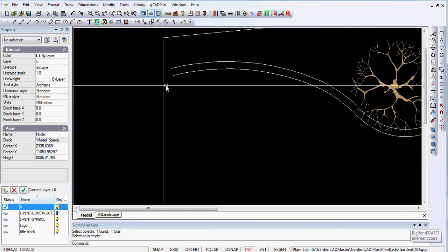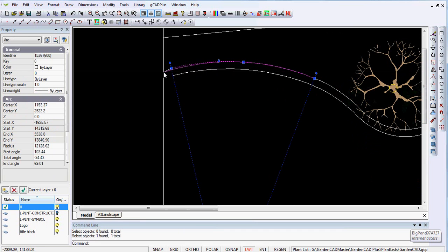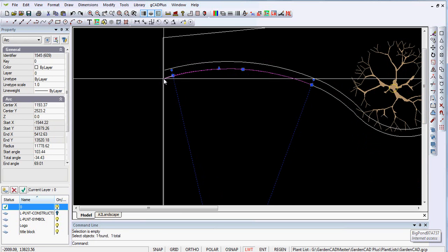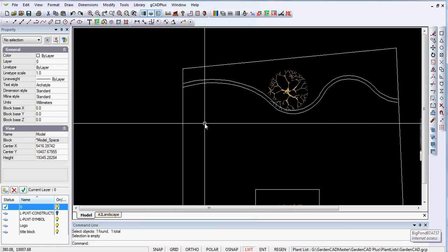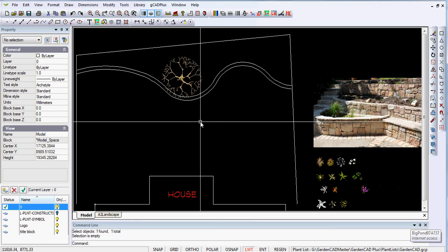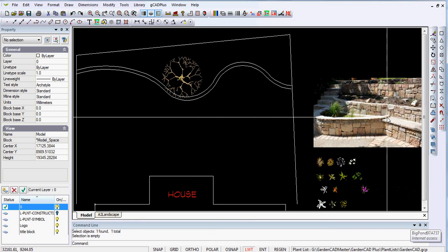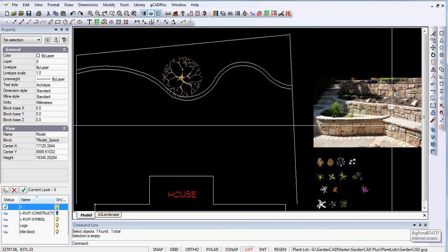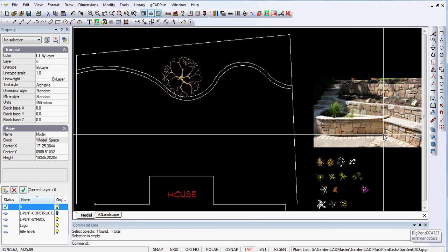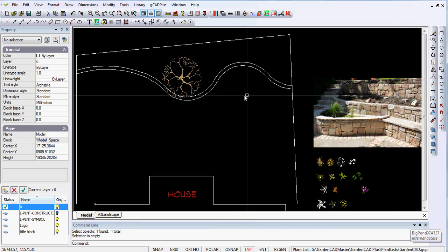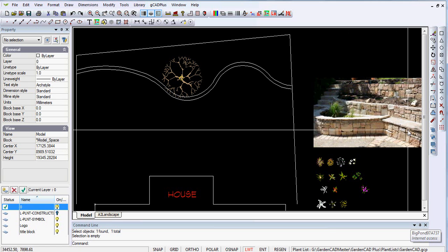such as this. The end of the arc could be extended quite easily by just clicking on it like so and bringing it out to close to that boundary. And you can see how I've got quite good control over the arc itself. So we now have a pair of compound arcs, if you like, delineating the sort of shape that we're going to have. Now you may notice that the flat capping stone protrudes over the edge there, so you could in fact offset again and create that sort of impression.